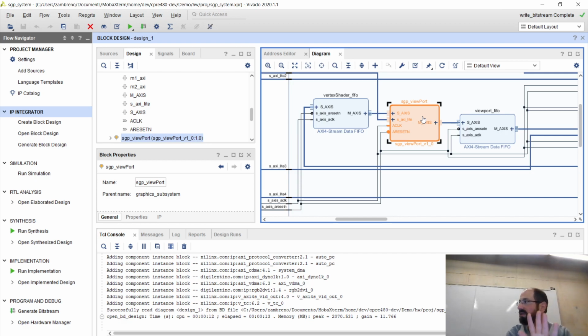You at least have that little bit of sanity that in software you can read this register value, confirm that this is actually core ID number 23, so that I'm not testing yesterday's logic, I'm testing at least today's logic. And then add whatever debug registers you want.